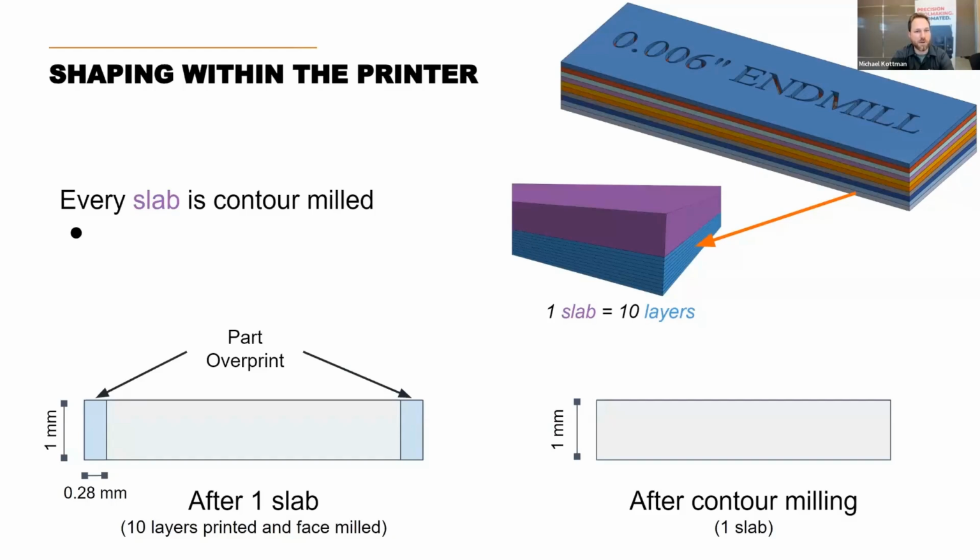Because we're doing it subtractively, we control the tool paths, so we can do deeper cuts where we don't get stair stepping. On vertical walls, you can do deeper cuts. As you go to shallower surfaces, we can do constant cusp, which gives you a consistent surface finish by doing smaller steps. It's much more like machining to a net shape conventionally, where you don't have the additive problems of what your resolution is during printing. Good point.